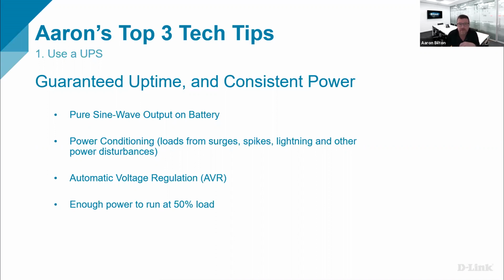So running at 50% of the size of the UPS you're after, that's also a very, very good figure. Now, one thing I forgot to mention is if you are using UPSs, check the batteries every couple of years. They should be either replaced or at least tested, because that is very mission critical. Because it's always when you kick over to the batteries that they fail.